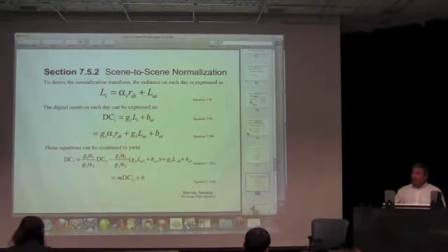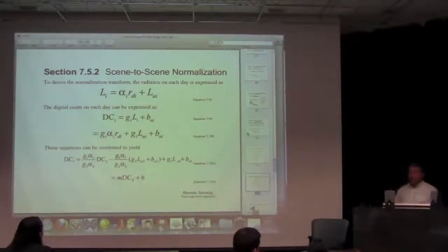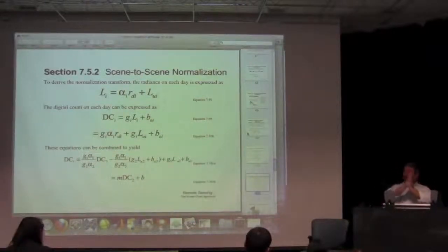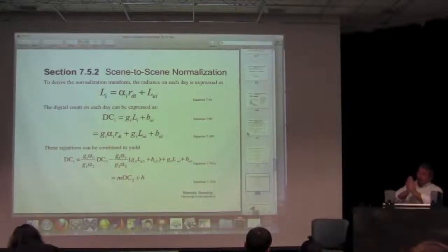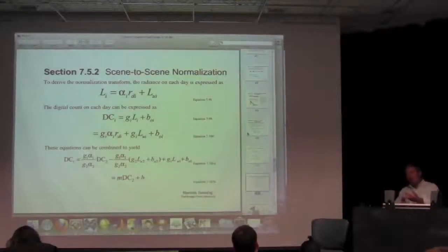So if your plan is to use that imagery to figure out what things might have changed in the scene, well, you could make that imagery lay pixel by pixel on top of each other by registering it or orthorectifying it. Right? So now you have pixels that are in the same locations. And then you can subtract those two scenes, and anything that comes out to be non-zero is something that changed. Well, there's a lot of things that can constitute change.